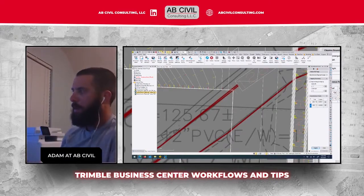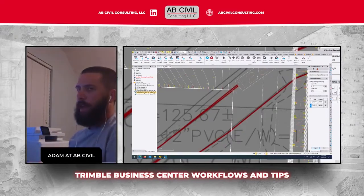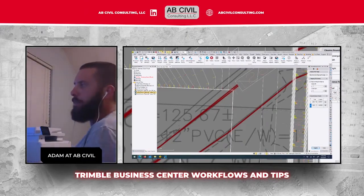If you type that command, it's going to say by default it's a value of 0, and you do a value of 1, then hit enter. It doesn't change anything for your file, but it allows me to import it into Business Center a little bit better. But there's no reason why I can't use a DWG and bring it into Business Center, even if it's a CAD file from the original designer. But that one setting is important for dragging into Business Center.